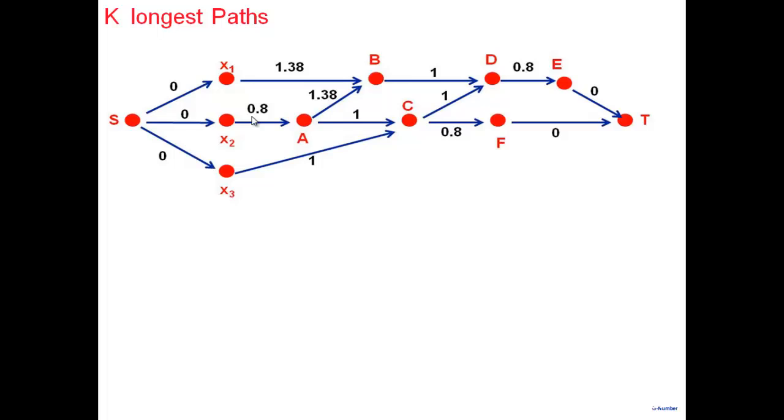But where is the delay? Where are these delays coming from? You started from the top, right? From the multiplier description, and you are systematically going, and you've arrived at the gate level description. Where do the delays come from? Gate has no information. A gate is just a block with two symbols, right? It has no information about delay. But I've not gone to the physical level, right? I've not gone. And I'm doing all this 1.38 and 0.8 and all that. Where is it coming from? I've not gone to the transistor level.